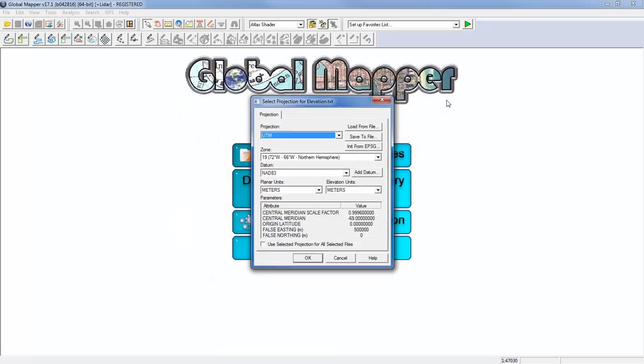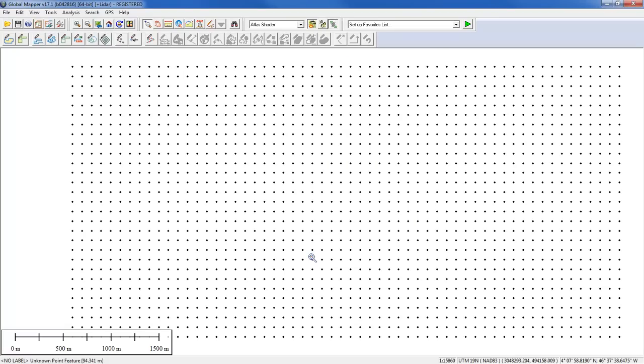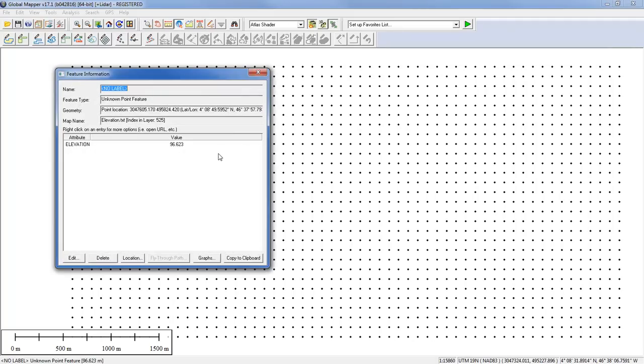The final setting, by the way, when I click OK, is to confirm the projection parameters. Now, in this case, it has remembered the settings that I applied previously. So this is a UTM projection that was the XY values, and the zone is zone 19 here in the Northeast US. So everything here is fine as well. We'll just confirm and click OK. And very quickly you can see now we have an array of points on our screen. These points are obviously very regularly spaced, or artificially created. They don't represent a typical source data set of this type like LiDAR, where it's more randomly distributed, but it does give us the basis for visualizing a process for converting simple point data into a surface. Now, to confirm, when I select an individual point, you'll note the elevation value is present right there.